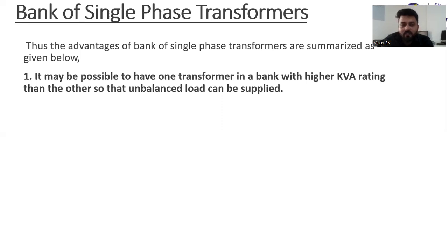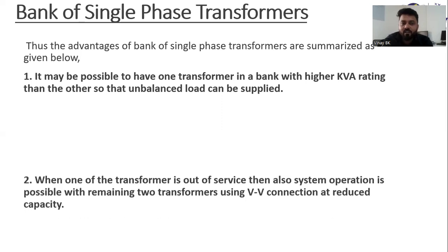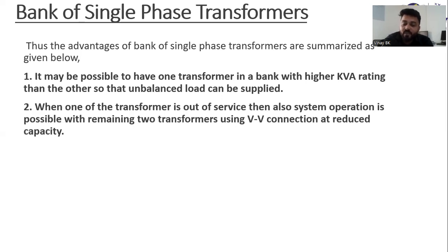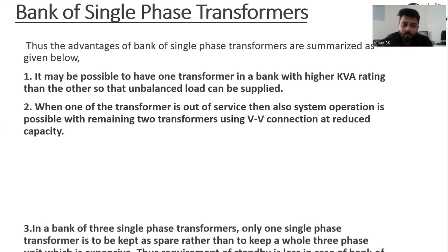Also, when one of the transformers in a bank of single-phase transformers is out of service, operation is still possible with the remaining two transformers using open delta connection at reduced capacity.